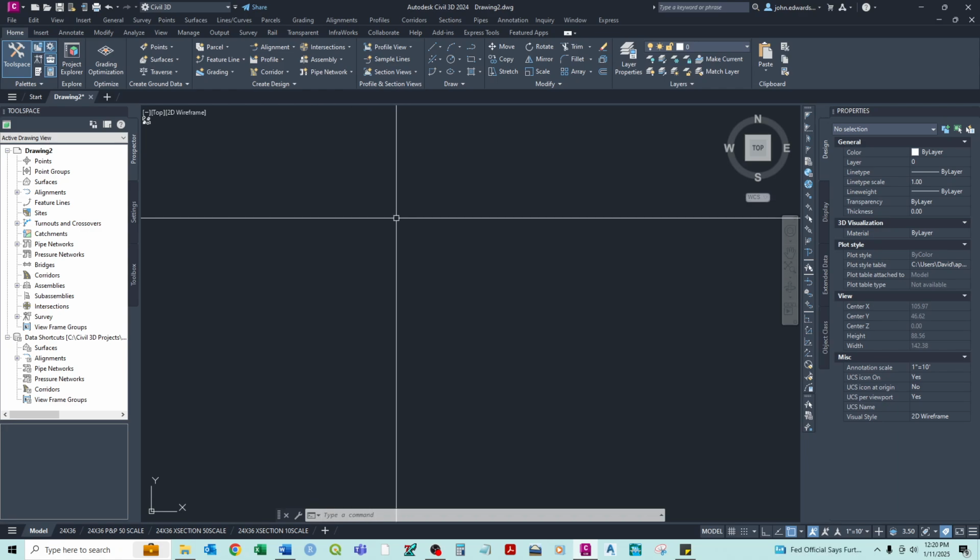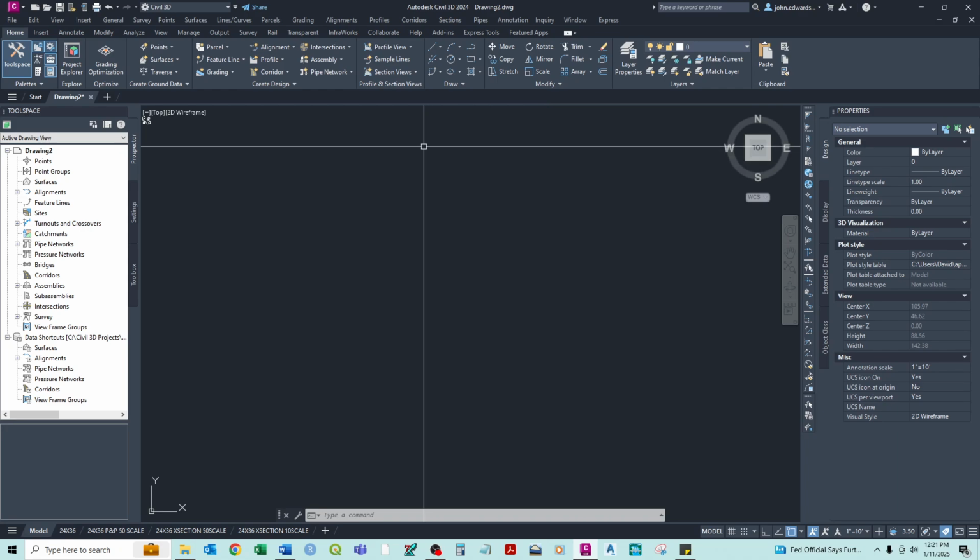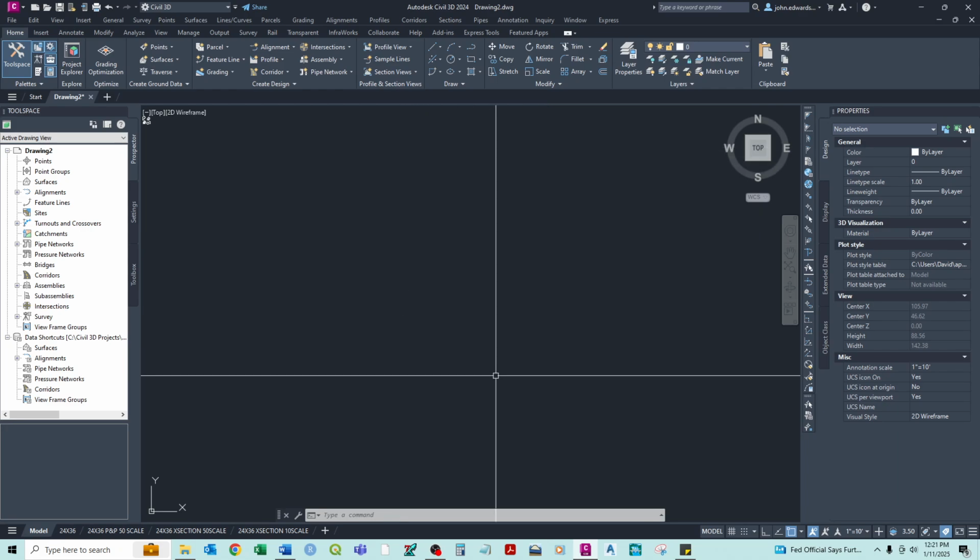Even though we could open the survey drawing file directly and source it, sometimes it's just easier to put it in. When the surveyor sends it to us, their drawing file has all of their standard layers and styles, but it doesn't include all of our layers and styles. That's one of the reasons we will create our own survey base, because our template has all of our layers and all of our styles built in, and it just makes things a lot cleaner.